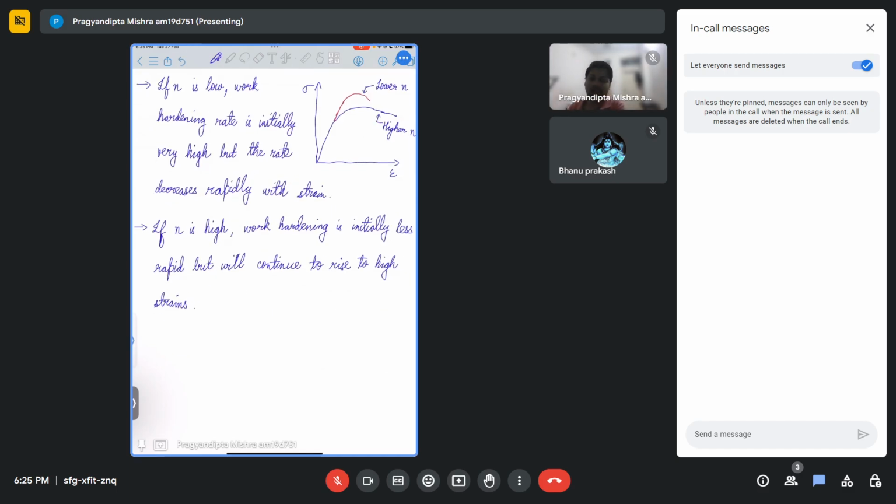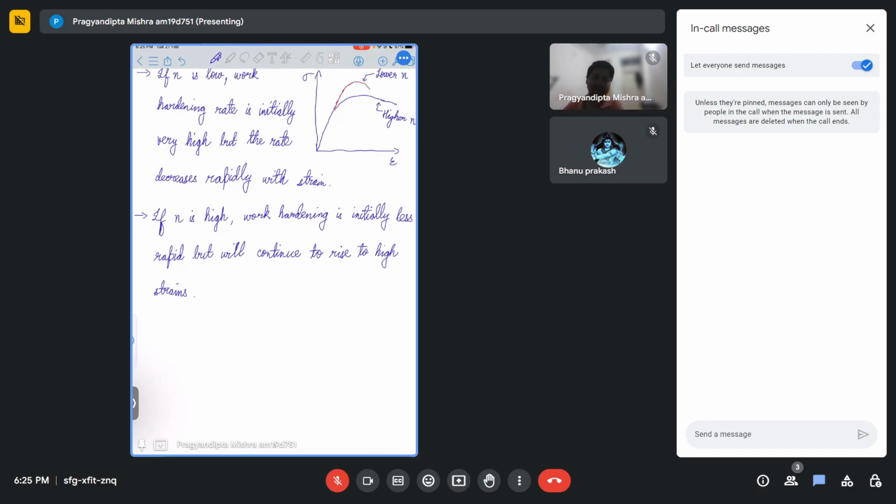So this is what we can take home from plastic instability. Anything else that is over and above this is another concept that we can talk about, but this much is sufficient for you to understand in terms of plastic instability. The major reason why we're studying plastic instability was to get an idea of what this value of n could be, right? Now once we know this n value, it is sufficient for us to understand anything in relation to flow stress. So the reason why we are understanding plastic instability is so that we can characterize this value of n.